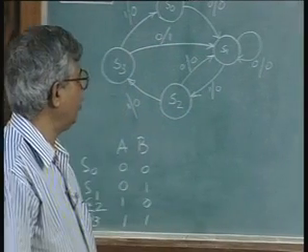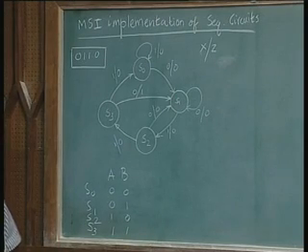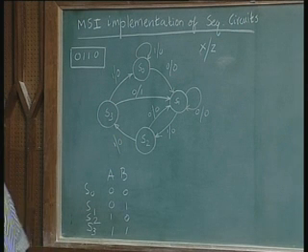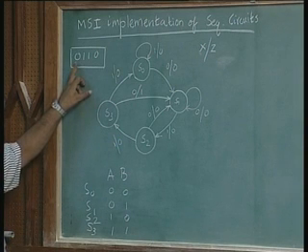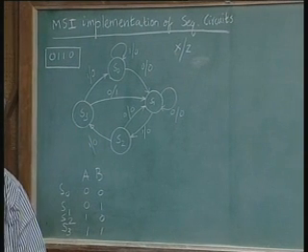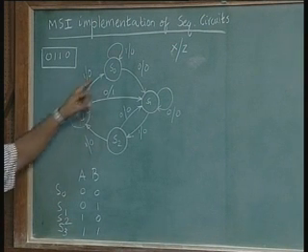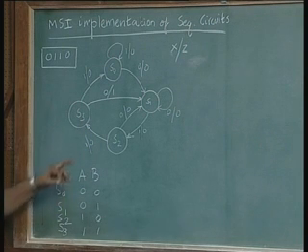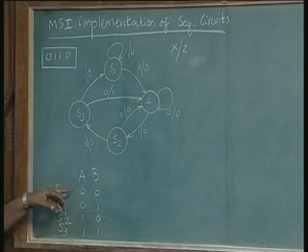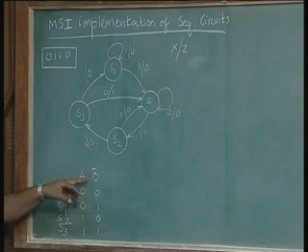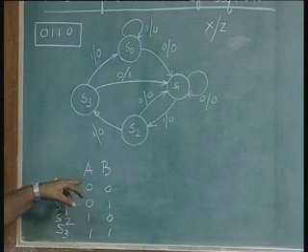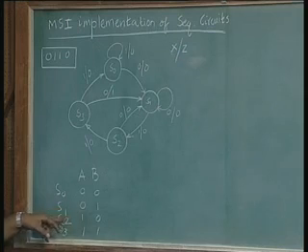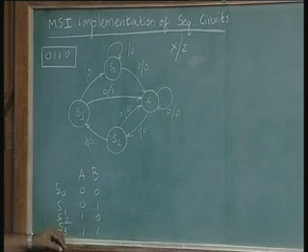In the last lecture, we developed a methodology to design a sequential circuit. Actually, we took a simple example of a sequential circuit, a circuit meant to detect a pattern 0 1 1 0 from a serial bit stream. For this circuit, we developed the state graph. This was the state graph we got, and there are 4 states in this, so I assigned state variables as A and B and assigned these values to A and B as given here: S0 0 0, S1 0 1, S2 1 0, S3 1 1. There are only 4 states.